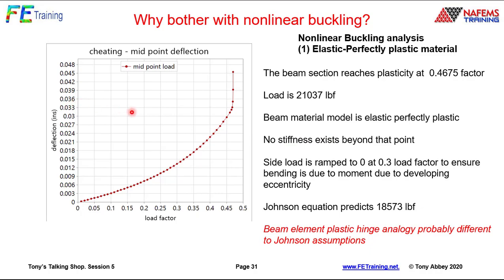Notice the deflections are very tiny. So the push load came off, I took it off. It still keeps that eccentricity building, and then it buckles at that point. So these are tiny little deflections now, not the bigger deflections we saw previously. In fact, I dropped that side load down to make sure that I wasn't interfering with the end result in here. So still not quite there, but that's about as far as I can go with the beam elements.